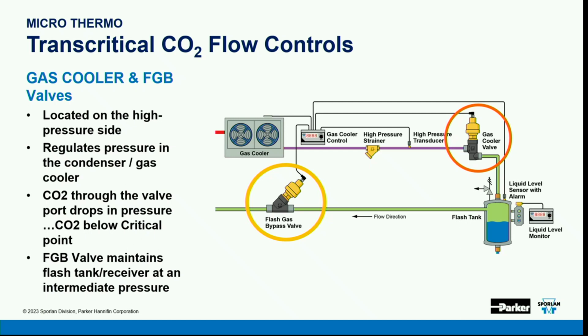What we do is we keep the receiver slash flash tank under the influence of the suction of medium temp, okay? That's the first thing we do. And we set that pressure. We say, we want this pressure in this tank to be 480 pounds, okay?